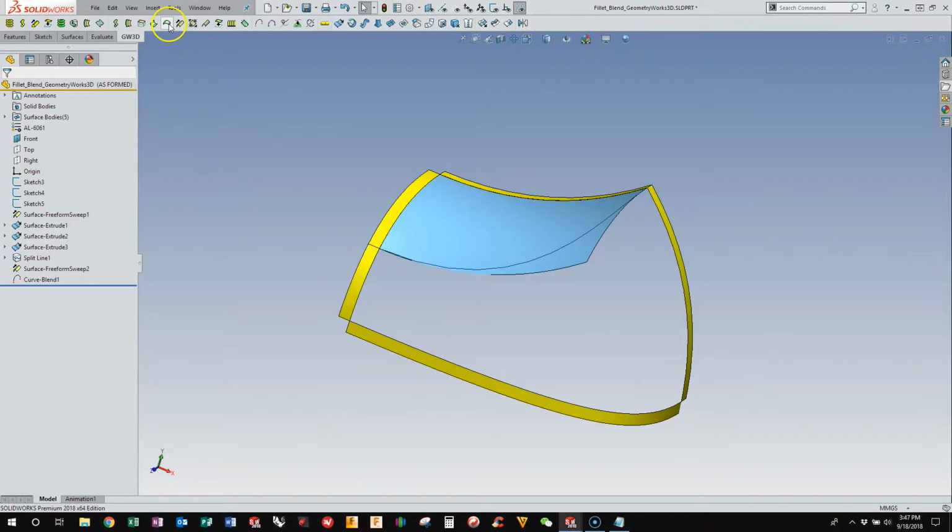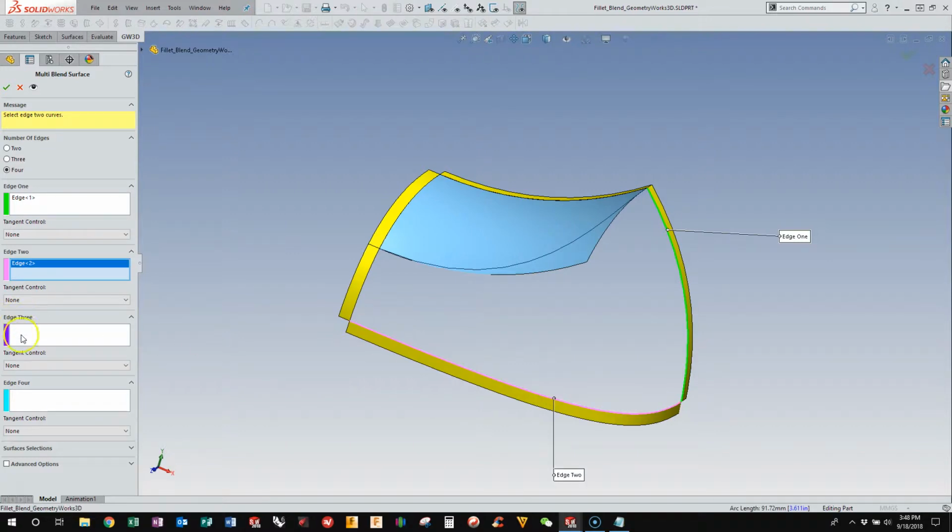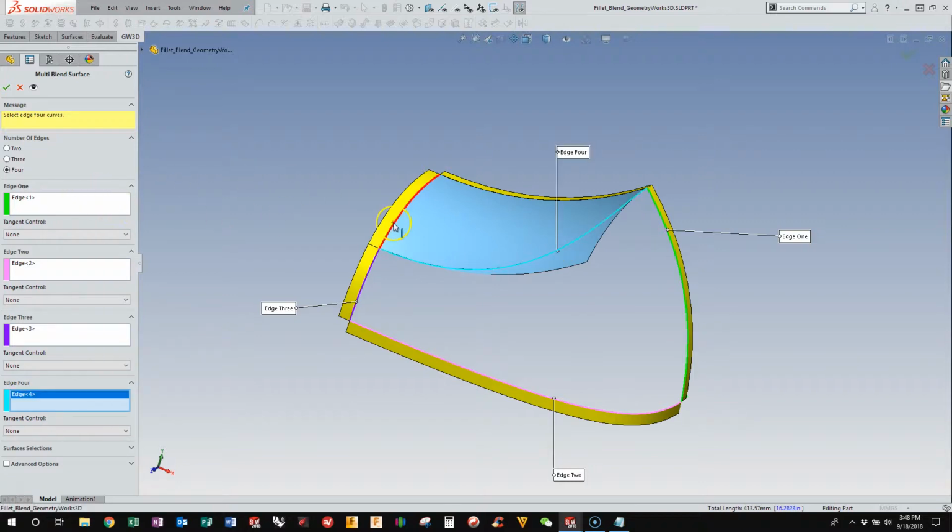And then they have this other feature, multi-blend. It's kind of similar to the boundary feature, it's just set up a little differently. And I've tested both of them. They do give different geometry and different results. Sometimes boundary is better, sometimes this one's better. I love having both of them, because if boundary fails, oftentimes this one works, and if this one fails, oftentimes boundary works. Don't know why, but having both of them typically allows me to get where I need to be.